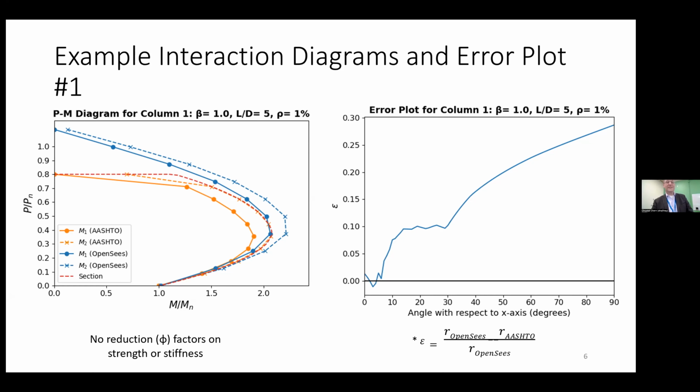Okay, but you can see from this that as we get to higher axial loads, right, the OpenSees models give us a higher strength, all right, indicating the AASHTO is conservative, if we assume that OpenSees is right. Claudio showed something about black boxes, dinging bells and stuff. I think he was referring to OpenSees in a very benign way.